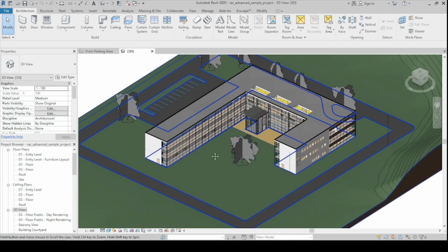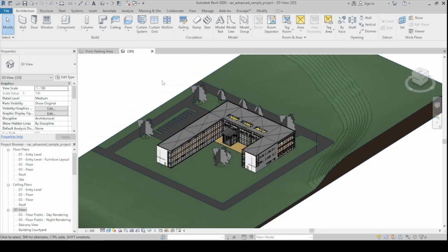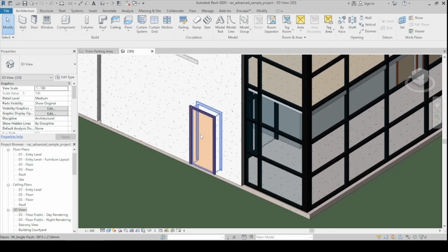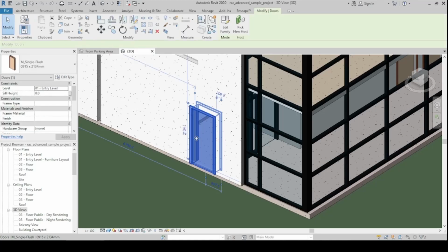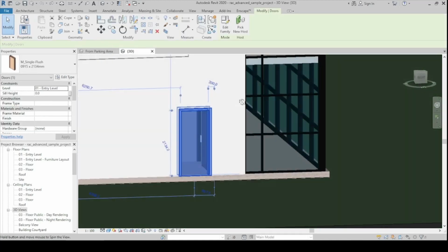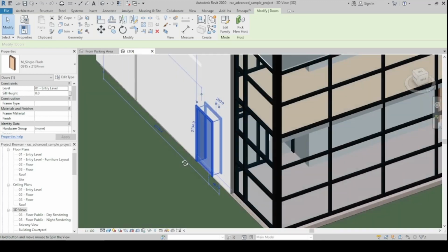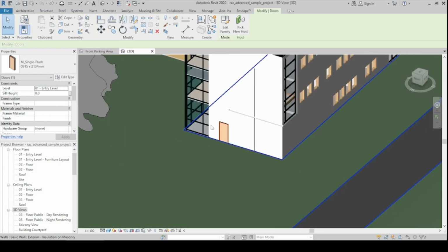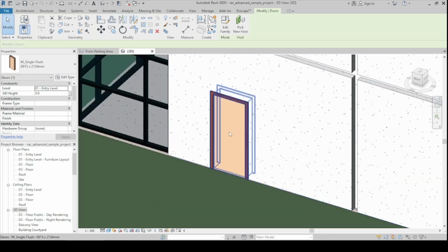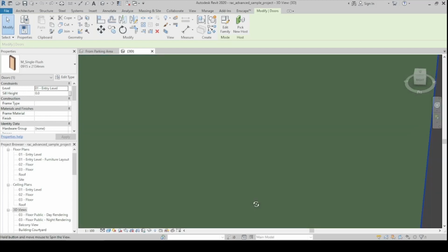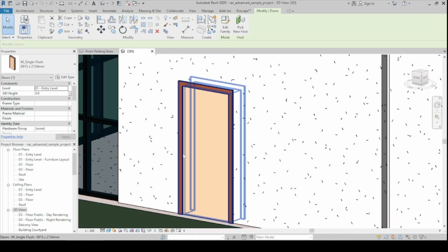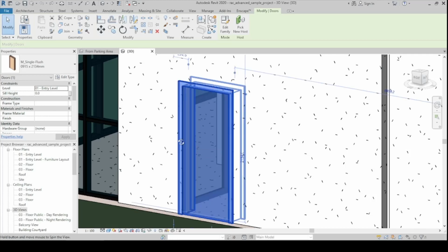Number two is, if you want to pivot in the 3D view, if you want to pivot a certain object, for example itong door, you need to select it first, then orbit. Okay, so that it will become the pivot of your orbit dito sa Revit, no? So let's say I want this to be an orbit and then hindi ko siya select una, and then if I orbit, nawawala kaagad siya sa view, no? So that's the main problem of the Revit beginners, nawawala sila sa 3D view because they don't select first the element and then view, no?